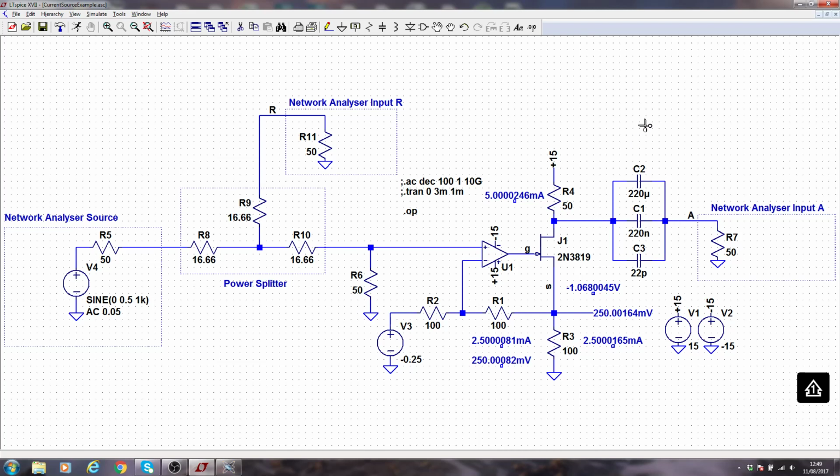If you don't, the network analyzer will probably trip at the input, or in the simplest possible case, a little fuse will go inside and you either have to reset it by pushing a button or physically remove it and replace it if it's a non-resetting fuse. Most of them have some sort of relay that opens and says channel A tripped, and you have to go in and press a button, and oftentimes it beeps as well to let everybody in the laboratory know that you've buggered it up. So that's the overall setup.